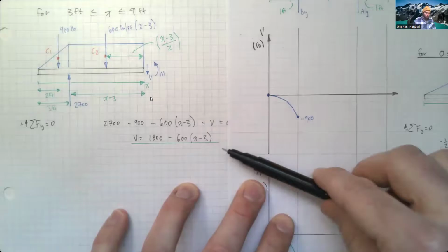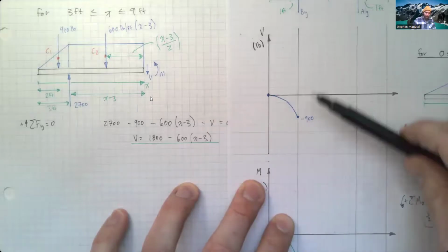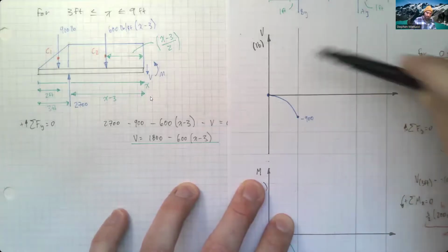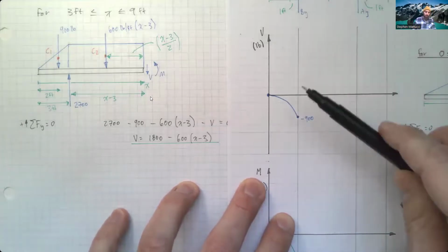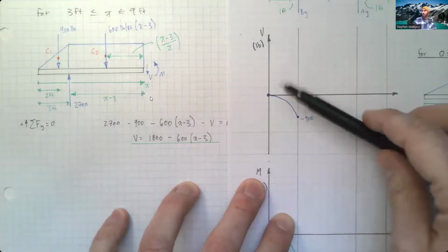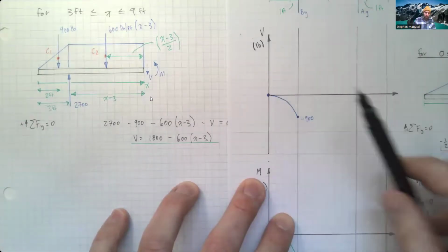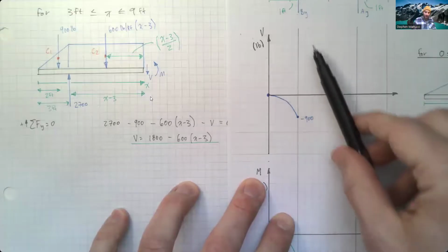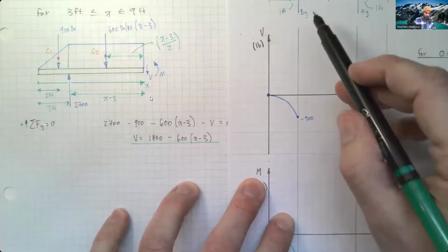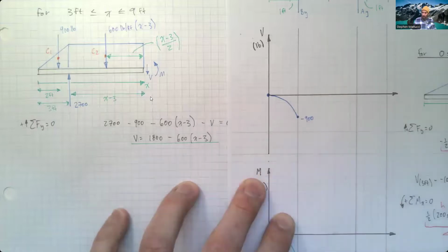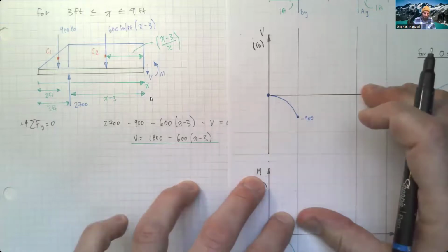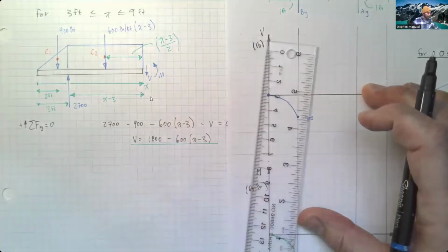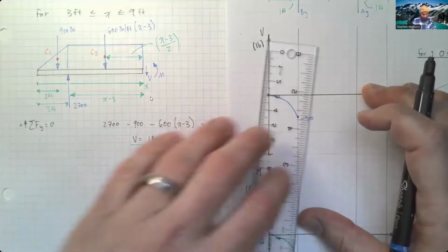Now, what I've kind of overlooked, and what we can't overlook when we're doing this, is what happens directly at this load. This is where we can interpret what's going on in our graph and just plot it directly on here. So we have a point load, a concentrated load, right at this reaction force. We know that's 2,700 pounds. So that's going to be a step in my diagram here.